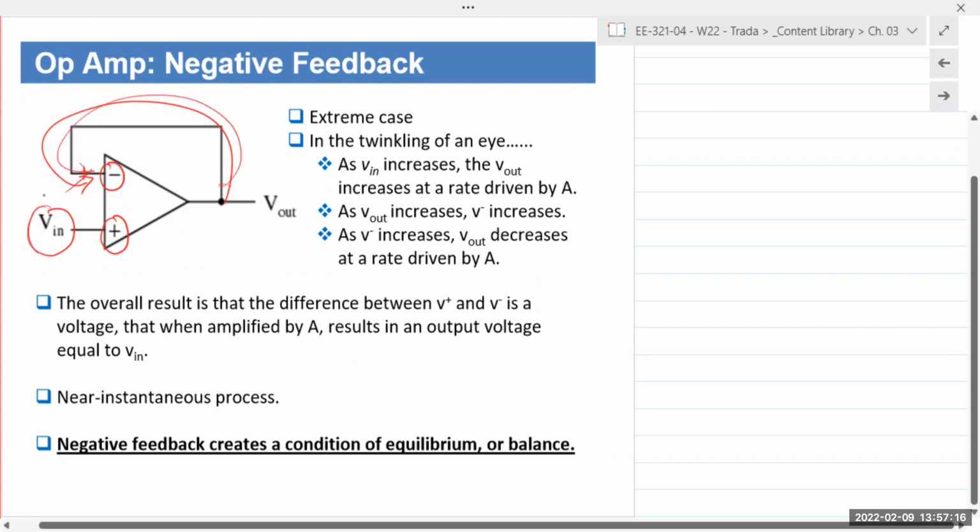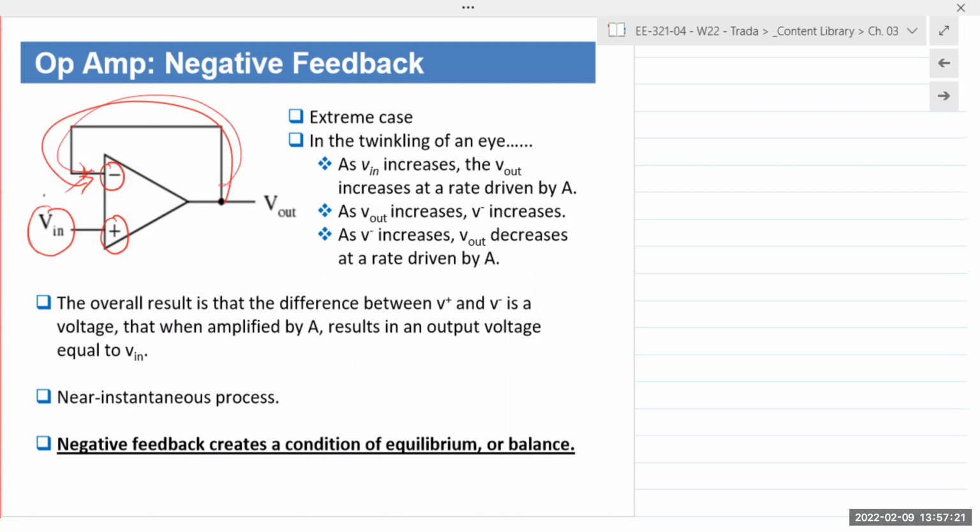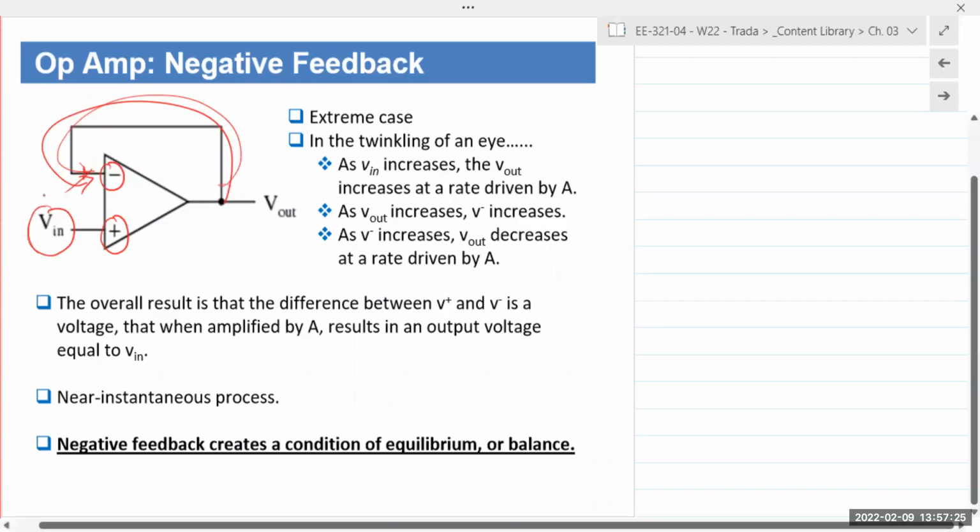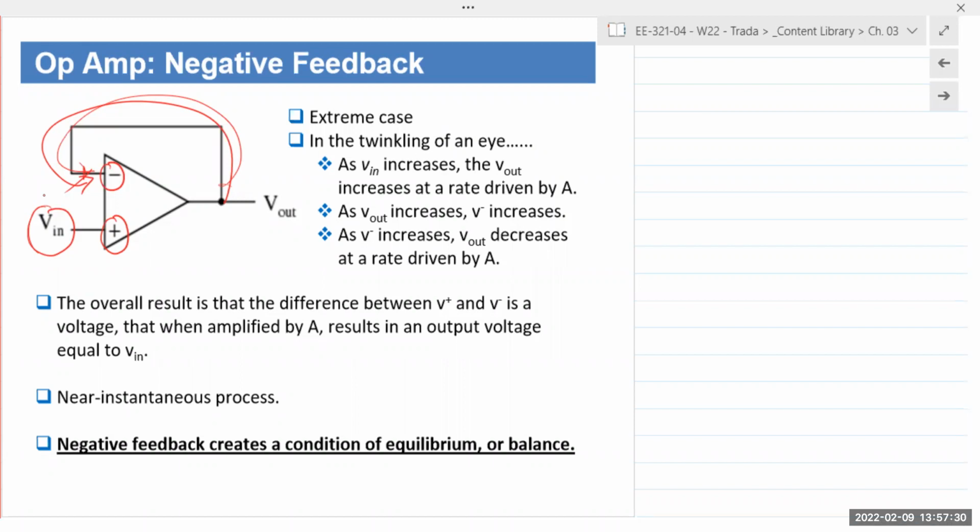So what happens then? It decreases, right? So when it decreases, it's going to take that small difference and again amplify it. Remember, common signals, zero amplification. Difference, even if it's a very small difference, will have huge amplification. So it'll take that small difference, again amplify it, and again send it back to the input. And that keeps happening constantly.